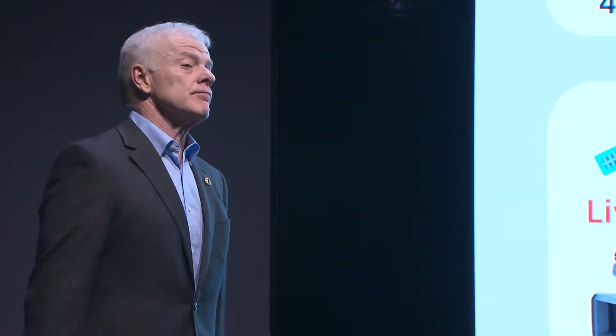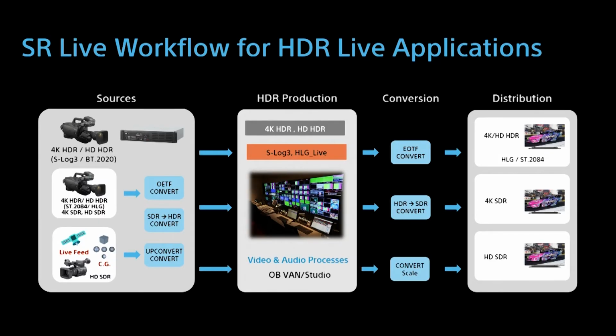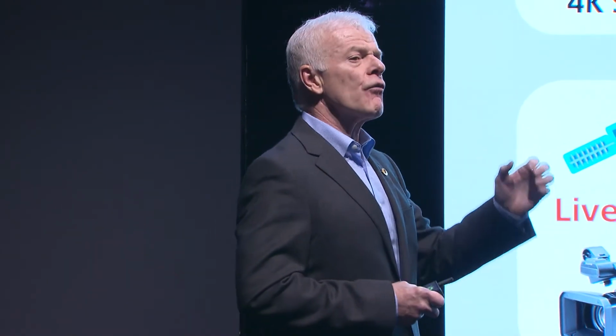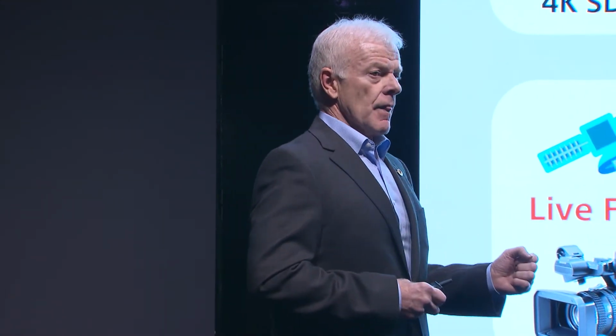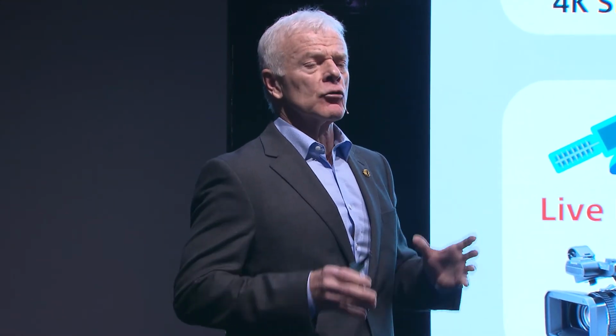Then this is your truck. This is an outside broadcasting truck. The truck consists of your video switchers, your monitor walls, your servers, your special effects, your audio console. That environment is defined as 1080p or 4K. And the color space will be 2020.